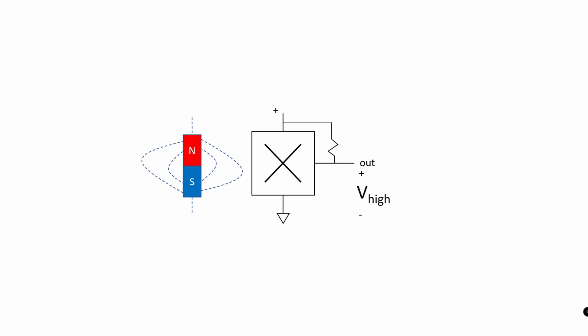To build a door sensor, we mount a sensor on the door frame and a permanent magnet on the door. When the door is open, the magnet doesn't affect the current trajectory and the current flows in a straight line across the sensor. When the door is closed, the magnet bends the current to a different location on the sensor, and that causes an event.